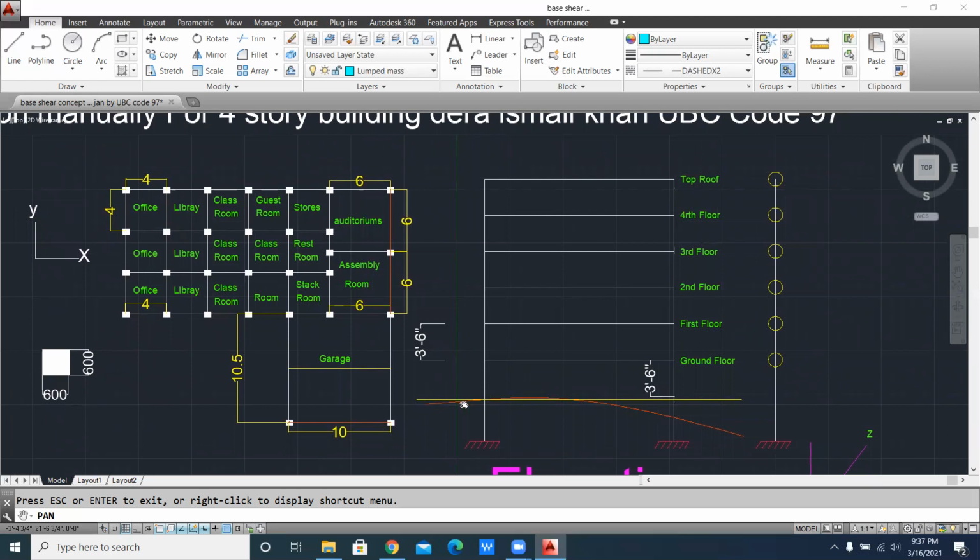First of all, you can drop this line. This one is a horizontal line. You cannot take the whole story height, that is, the story is 3.5. You have to take this half and lump it into this, then this half, and add these two together, then lump into this. Then this half is lumped into this, and this half is then lumped into this. This portion will only be remaining up to the top roof. These are basically the lumped forces.